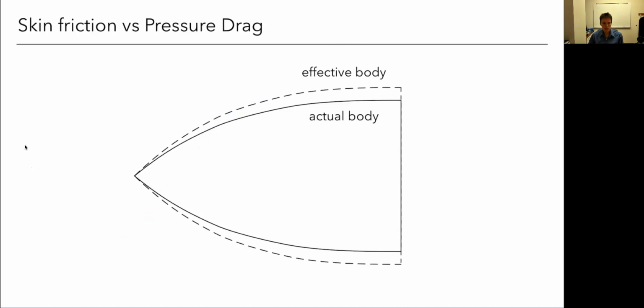One thing to keep in mind, and we'll bring this up again later as we start to couple what we're doing now with panel codes, is that the presence of the boundary layer has changed what we could call the effective body. Because I have this boundary layer that's slowing the fluid down, it's kind of like I've made my body bigger, right? A bigger body would also have less mass and momentum flow around it. And so it's not exactly the size of the boundary layers we've discussed. We'll talk next week about some different ways to measure boundary layer thickness related exactly to this idea. But because there's some slowing down, we're extracting or losing some mass momentum in that boundary layer,